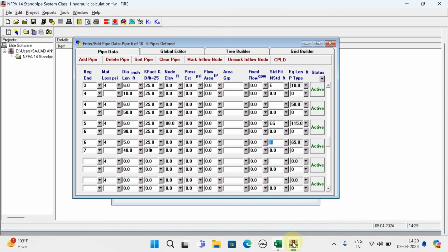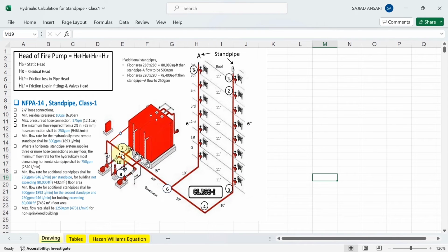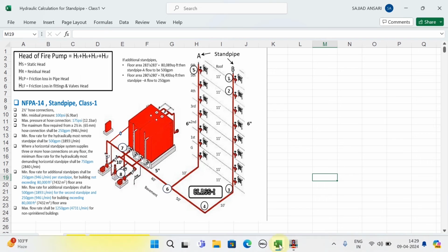Okay. Then finally, when you open the Excel sheet, from 7 to 8, now pipe size is 5 inch only. Total length is 10 feet. Elevation, it is going down. So let's say minus 10 feet. Okay, elevation you can take as a minus. Suppose this for this pipe. Okay, first see, I will fill this detail.